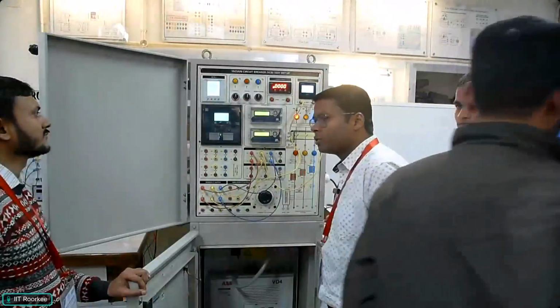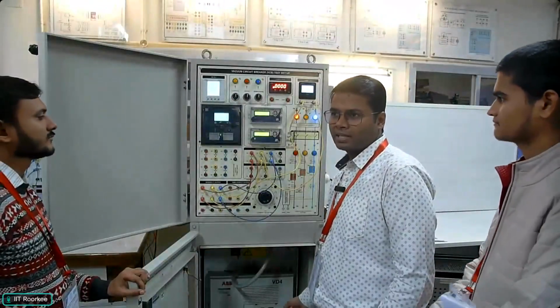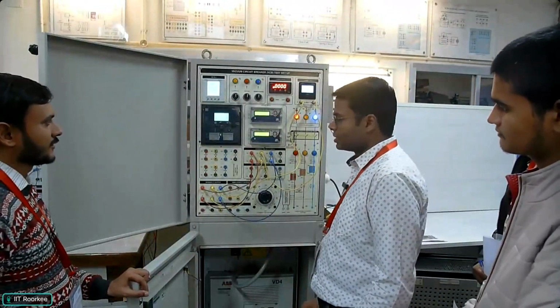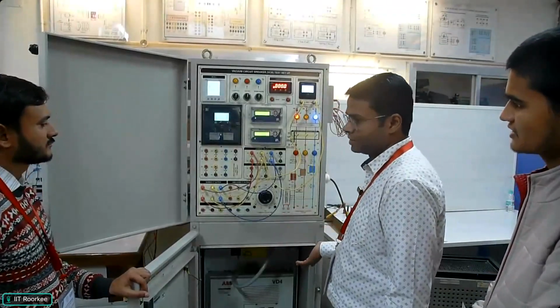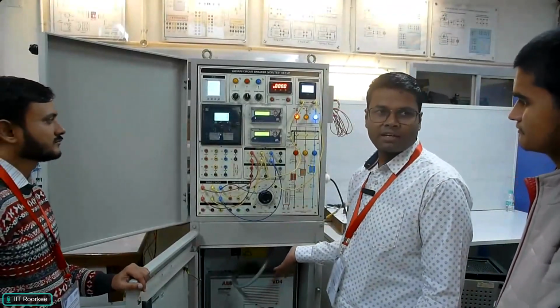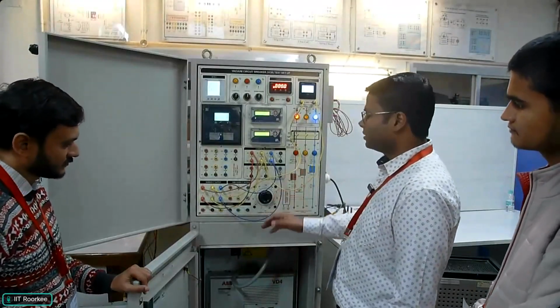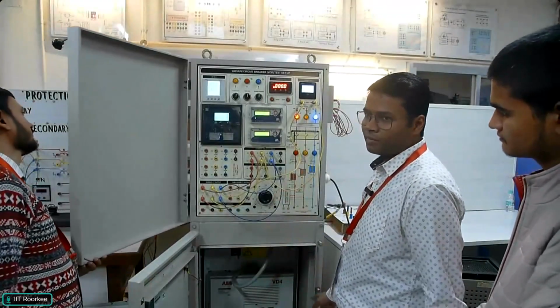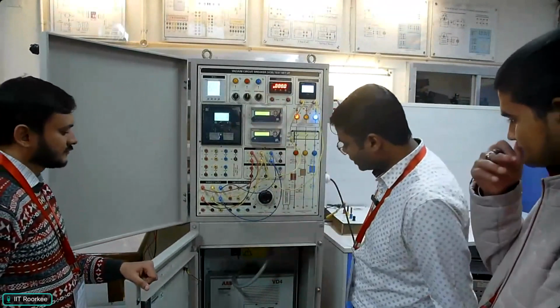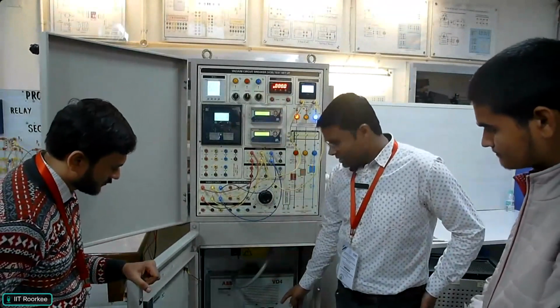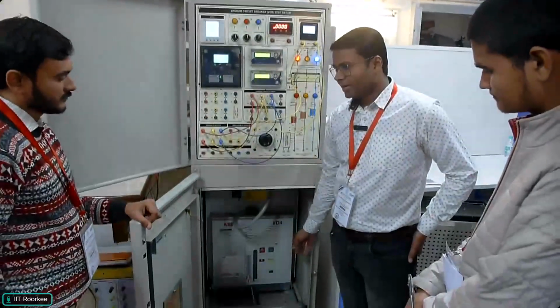In the mechanical part we have two types of spring. One is the closing spring and the other is the trip spring. One will be charged at a time and the other will be discharged at a time. A bias will come when I do the closing operation through automatic or manual. In manual condition, you can see that it is in off mode, trip mode.